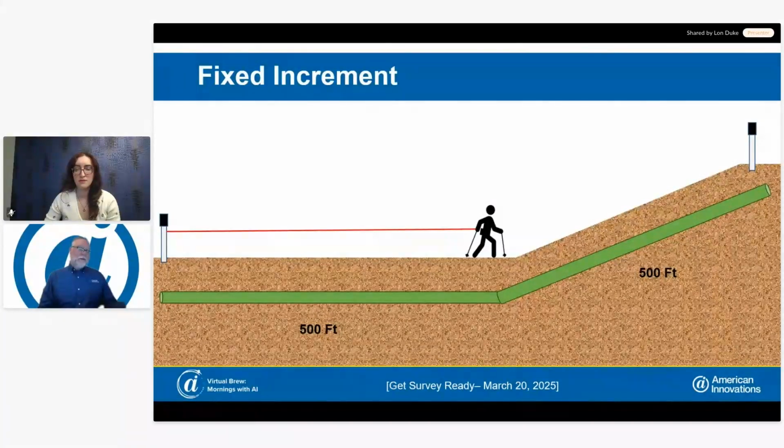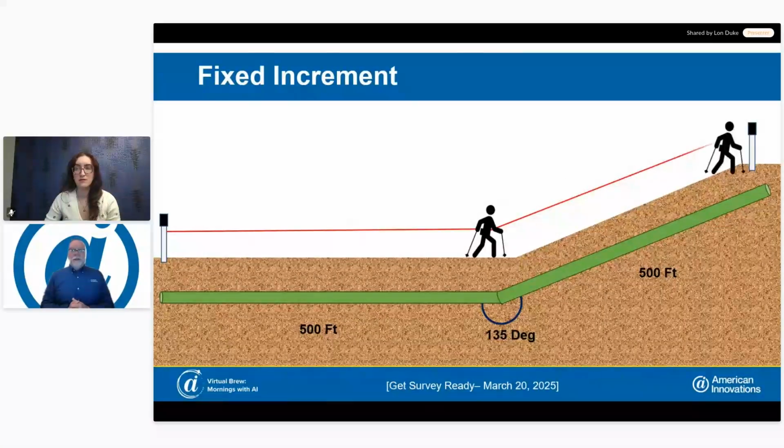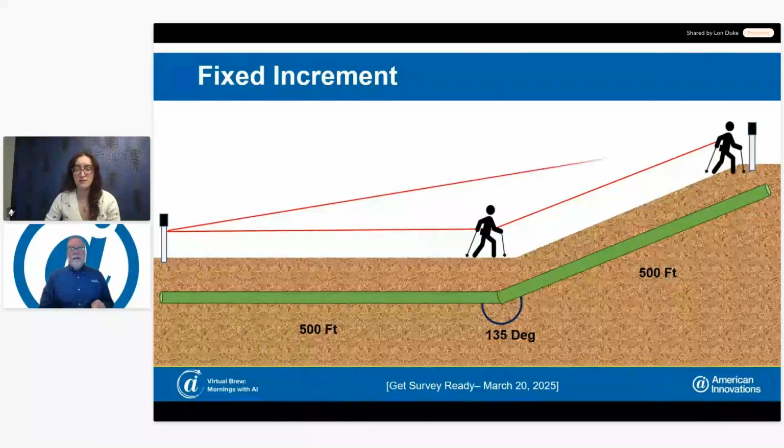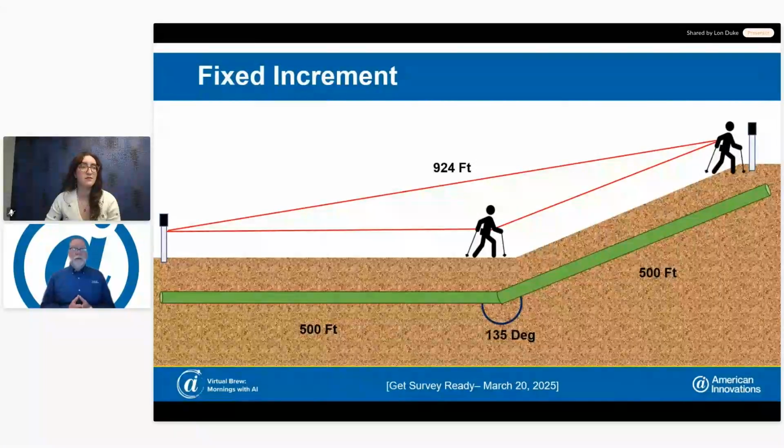It could be just going lateral or it could be going up. If I have that bend in that pipe and I'm walking along doing my survey and I get to the end of it, I should have 1,000 feet on my survey. But if I don't anchor that down where that bend is, that survey wire is going to come up with me and I'm going to lose footage. So in this case, we're over 70 foot short on 1,000 foot.